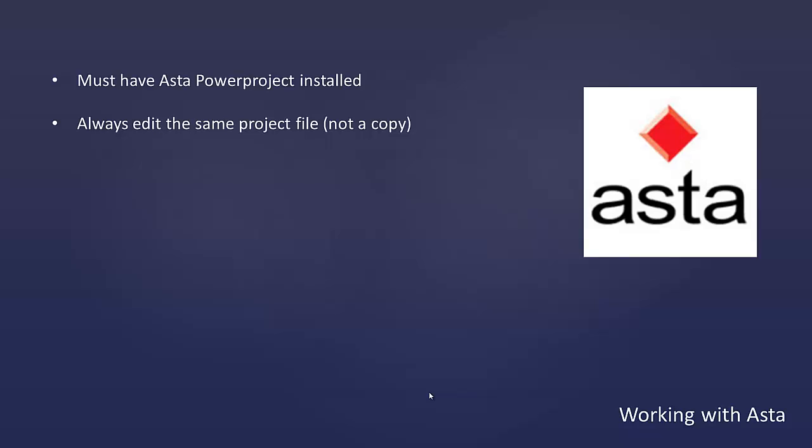So if you continue making changes in parallel to two different files, you may end up with different IDs, and those IDs for one task in one project may be on a task, and in another project it may be on a resource. And so when Synchro tries to update from a different copy of that file, it doesn't know how to treat those IDs. So we recommend just always working from the same project and never working in parallel on two different files.